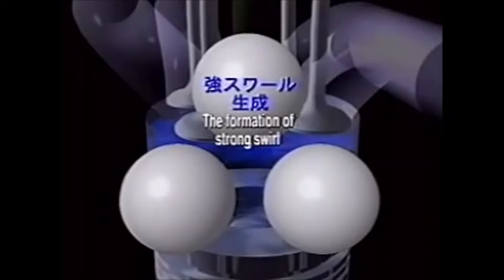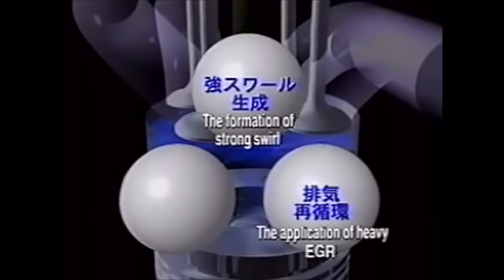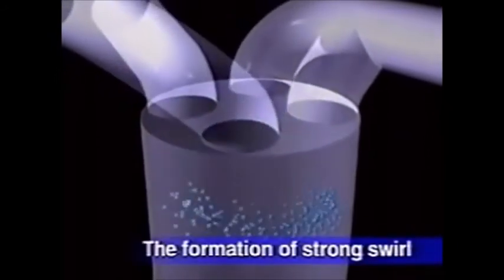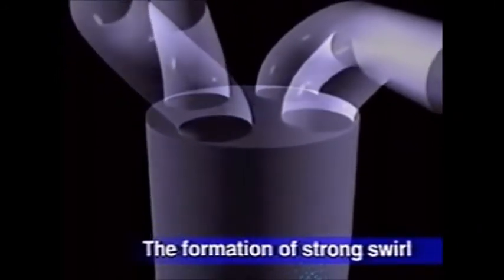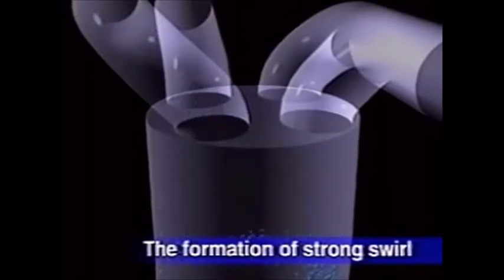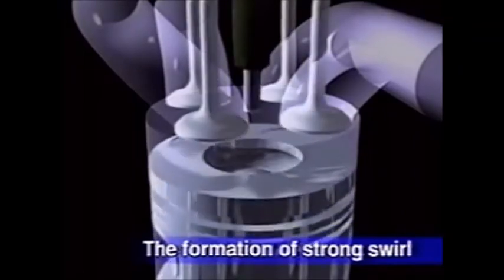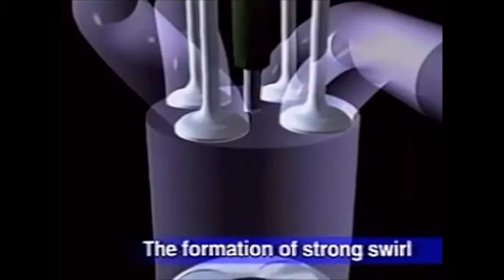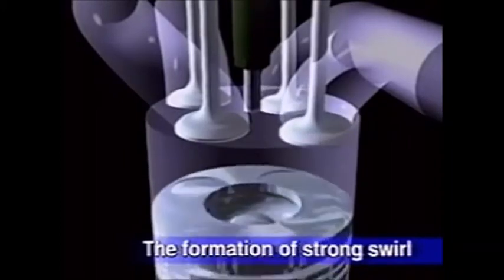These technologies are the formation of strong swirl, the application of heavy exhaust gas recirculation, or EGR, and optimization of the fuel injection timing. A newly developed helical intake port is used to generate stronger than ever swirl motion in the air in the cylinder. The fuel spray is injected under high pressure into this strongly swirling air, enabling the fuel and the air to be thoroughly mixed.